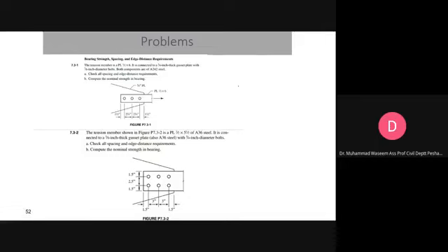Now, in this case, A36 steel is not used, but we have A242. You will be asking, what is the Fu for A242? For A242, the ultimate strength of the material is 70 ksi. This tension member is a plate, and the thickness is different. Which will be controlling for the bearing strength of the connection, the gusset plate or this tension member? Gusset plate, because it has less thickness.